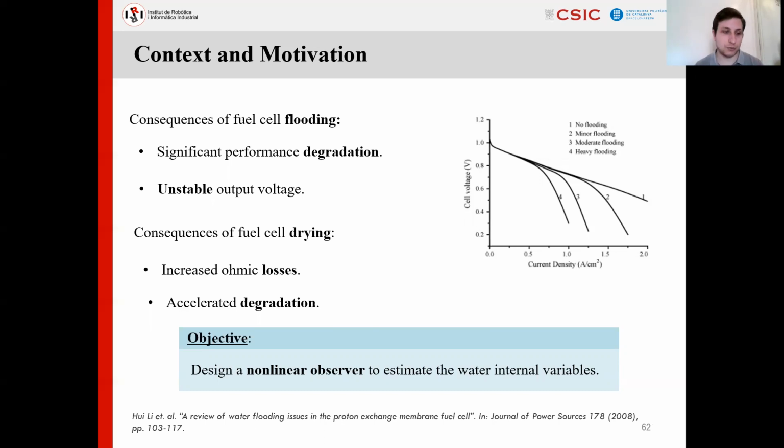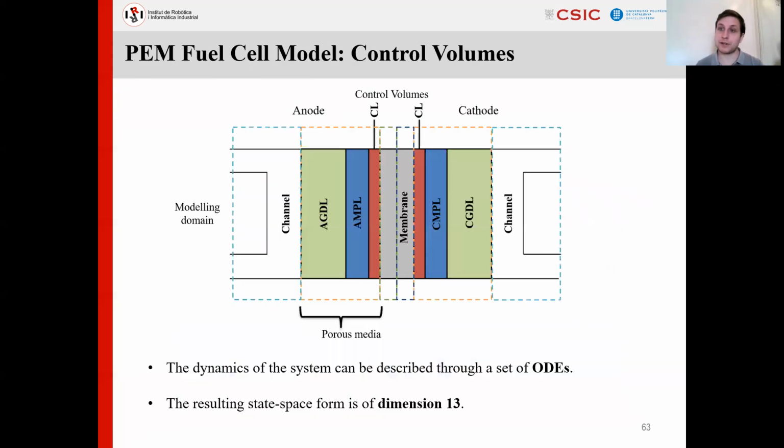It should be remarked that fuel cell dynamics are related to models with strong nonlinearities and a significant amount of uncertainty. This is why it was crucial to deploy more advanced observer theory and even extend the available theory. So as a first step, in order to design the observer, it is crucial to have a model for the fuel cell system. And this thesis started from the governing equations that depicted the dynamics of the oxygen, the water vapor, the liquid water saturation, the water content, and the temperature.